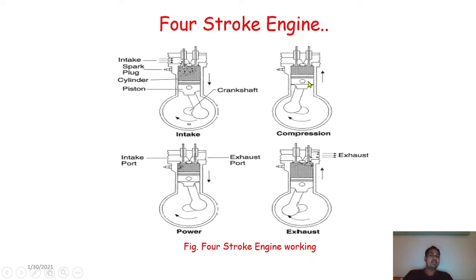Up to this suction and compression, no kind of burning takes place. Only the piston is moving from TDC to BDC and BDC to TDC because of the self inertia. I think all of you know an example of self inertia. Take the example of your bicycle: whenever you apply pedal pressure, and then you release the pressure or effort from the pedal, it will still rotate for some duration. That is the example of self inertia.